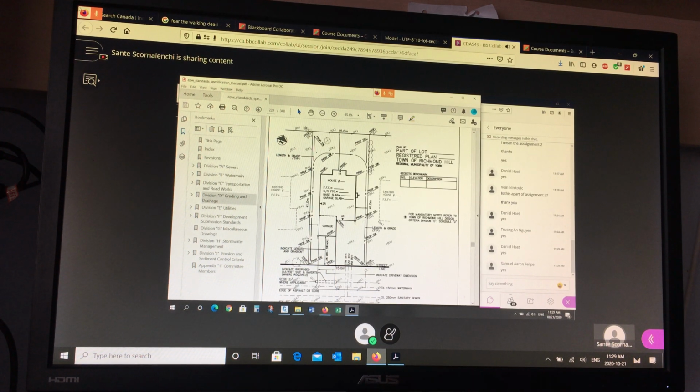This is the elevation at the back, this is the elevation at the front lot corner. So at the end of assignment 3, you're going to have elevation at the front of each corner and at the back of each corner. Okay, and then what we do in between the front and back is our responsibility. What happens inside the lot, all the proposed corners of the house and so on, that's usually the architect. We would review and certify that, but we wouldn't design it. We're only designing the perimeter, along the lot line, at the front, at the back, and along the sides. So that's our only responsibility.